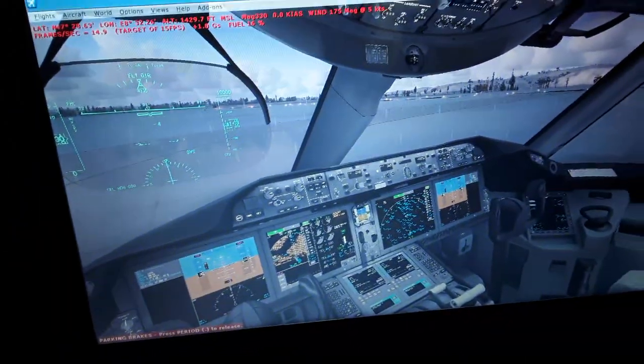You can see also the navigation aids, the navaids, which are the VORs, ADFs, and DMEs, and the waypoints. The waypoints, which are horizontal and vertical navigation fixes and altitude and speed constraints. We have to fly through some waypoints. As I told you, we're going to set up a complete flight plan in the flight management computer later. One by one, each waypoint is going to be connected with a purple magenta line. You will see it in the navigation display. We can connect also the autopilot when we fly using the flight management computer flight plan we're going to create.